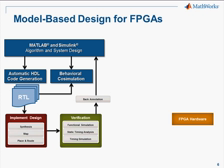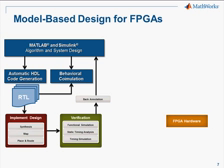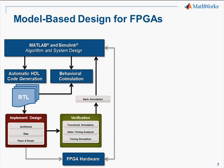You also have the ability to drive the downstream FPGA tools, such as Altera's Quartus 2, and to run verification using HDL simulation. You have the ability to back annotate the timing information into the original Simulink model, and you have the ability to drive down into FPGA development board hardware. So again, you're working off of a common design description, and you're driving the entire design process, giving you greater ability for iterative design improvement.